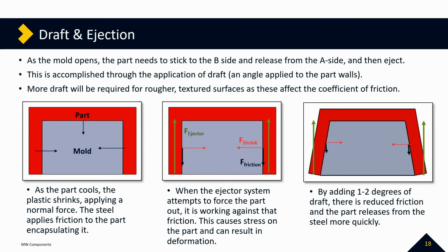If you're looking to do that, not in the context of a contract molder, you could go to a machine shop and as long as you're going there with a certain frame size, you can get something called a mud frame, a universal frame. You would just go to a machine shop and say, I need 2 pieces of steel with water lines cut through them with this kind of area untouched where I can actually make my part.